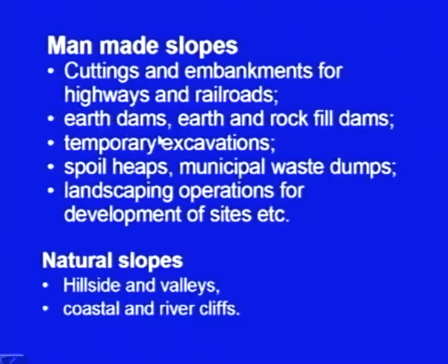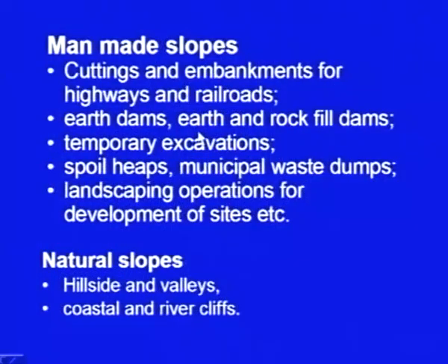Then there are earthen dams and earth and rock fill dams. A dam is a structure which is constructed across a river, and the purpose of the dam is either to divert the water or to store the water during the monsoon season. It is a very important structure constructed in the river, and it has to resist a huge amount of forces due to water, and forces due to some other agencies also. The dams, if constructed of earth, may be earth dams, there may be earth and rock fill dams, and there may be gravity dams also.